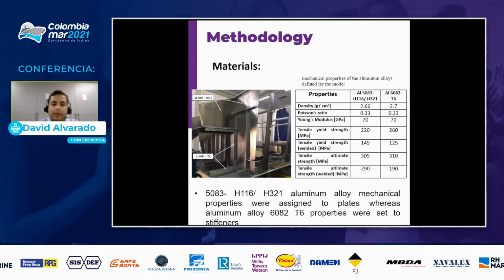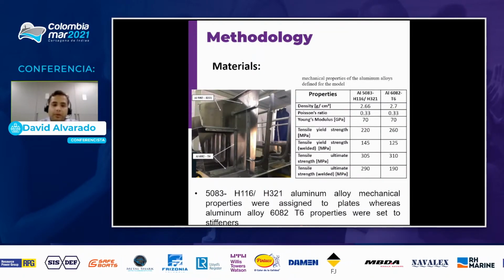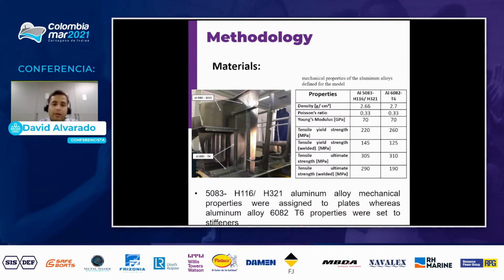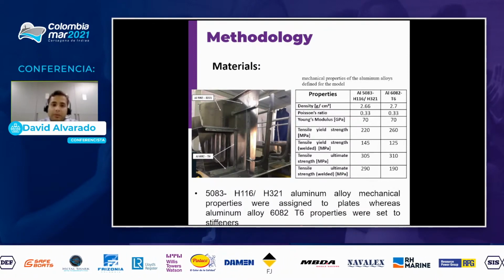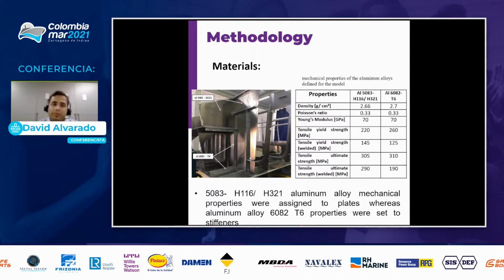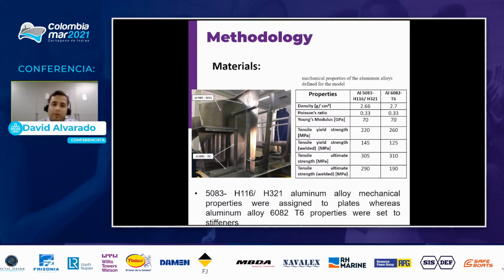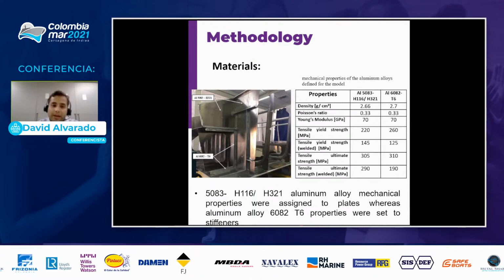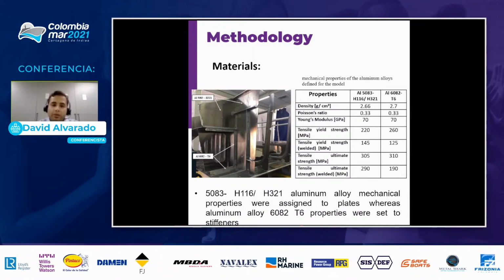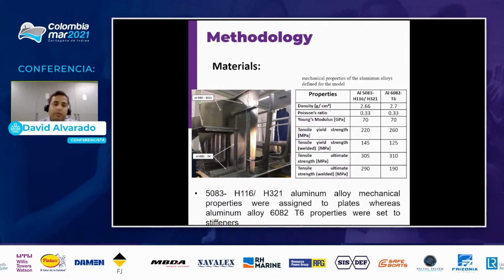Now, firstly, there are materials. As I said before, aluminum provides us with a light vessel with a high weight resistance ratio, but there is a problem with high temperature gradients from welding. Its mechanical properties, in some cases, are reduced down to half.